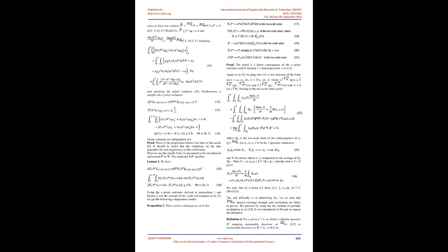In the modeling of the underground transport, the first question is how to handle the fluid flow. In all models reviewed in 23 and 15, and further studied in 14, we remarked that the concentration of the transported contaminants is such that the flow is not affected. This means that we should study the effective flow before looking at the mass balance equations for the transported species. All flows could be considered as incompressible.